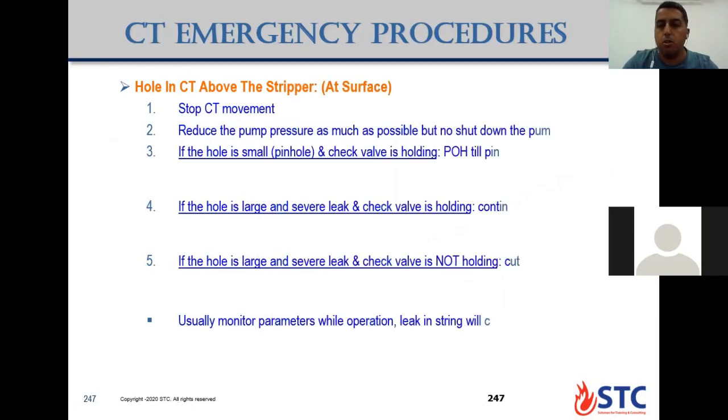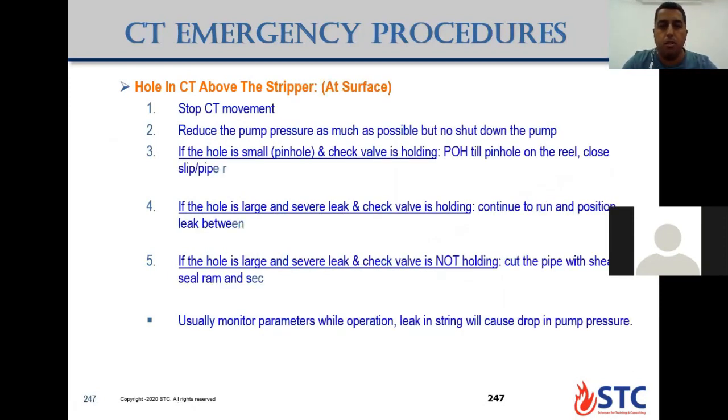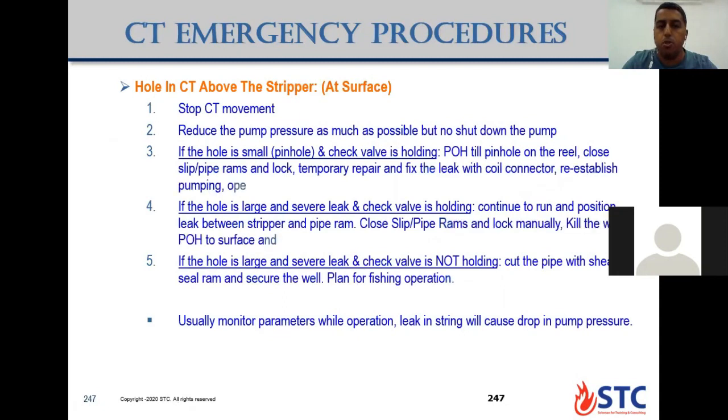First action, stop coil tubing movement. Number two, reduce the pump pressure or pump rate as much as possible, but do not shut down the pump. You need to see how the leak is at the surface. If the hole is small, like a pinhole, and the check valve is holding, so you have bled pressure, the check valve is holding pressure, no buildup at the surface. In this case, you are in a somewhat safe condition.